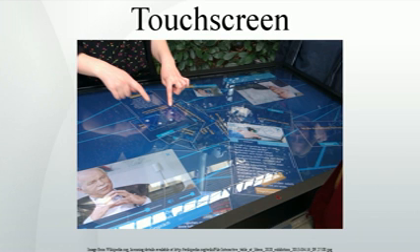Projected capacitance. Projected capacitive touch, PCT, also PCAP, technology is a variant of capacitive touch technology. All PCT touch screens are made up of a matrix of rows and columns of conductive material, layered on sheets of glass. This can be done either by etching a single conductive layer to form a grid pattern of electrodes, or by etching two separate, perpendicular layers of conductive material with parallel lines or tracks to form a grid. Voltage applied to this grid creates a uniform electrostatic field, which can be measured.